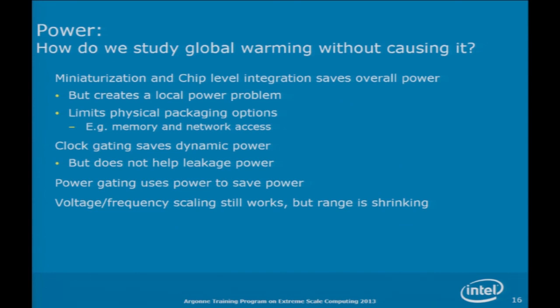Voltage frequency scaling, that's sort of how, before most of you were born, actually MOS gates, you always used 5 volts to power them. We basically scaled power downwards, and now it's less than 1 volt. Since the dynamic power is basically a factor of 2 or maybe 3, it's the voltage supply. Voltage to the power of 3 determines the dynamic power, and so that's a big deal.